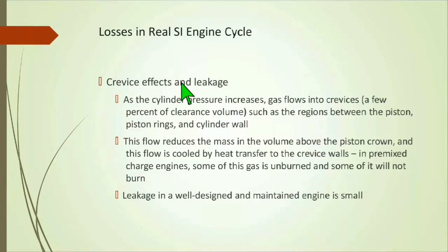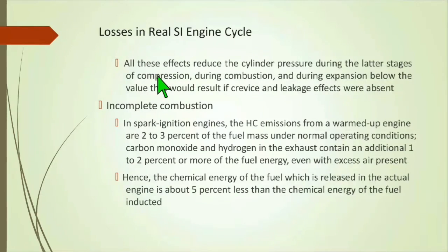Crevice effects and leakage. As the cylinder pressure increases, gas flows into crevices, a few percent of the clearance volume, such as the regions between the piston rings and cylinder wall. The flow reduces the mass in the volume above the piston crown, and the flow is cooled by heat transfer to the crevice walls. In premixed charged engines, some of this gas is unburned and some of it will not burn. Leakage in a well-designed and maintained engine is small. All these effects reduce the cylinder pressure during the latter stages of compression, during combustion and during expansion below the value that would result if crevice and leakage effects were absent.